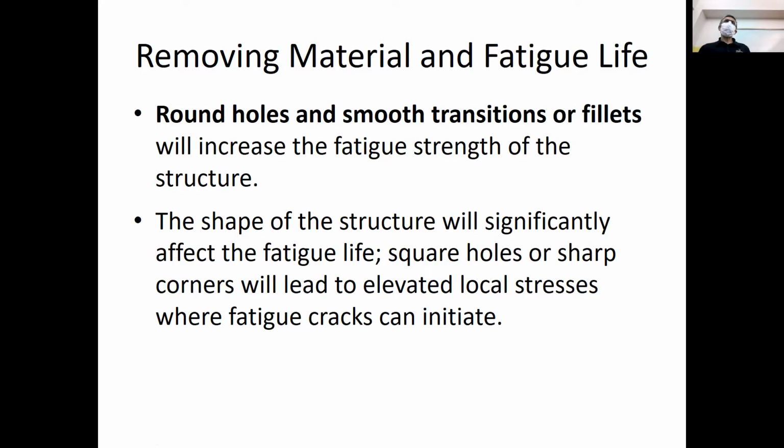Before I get into the S-N diagram, I want to remind you that with fatigue, surface finish is extremely important. If you have a part that's going to be subject to fatigue, we want to make sure that it has as smooth a surface as possible. Why? Because stress concentrations are going to lead to failure.